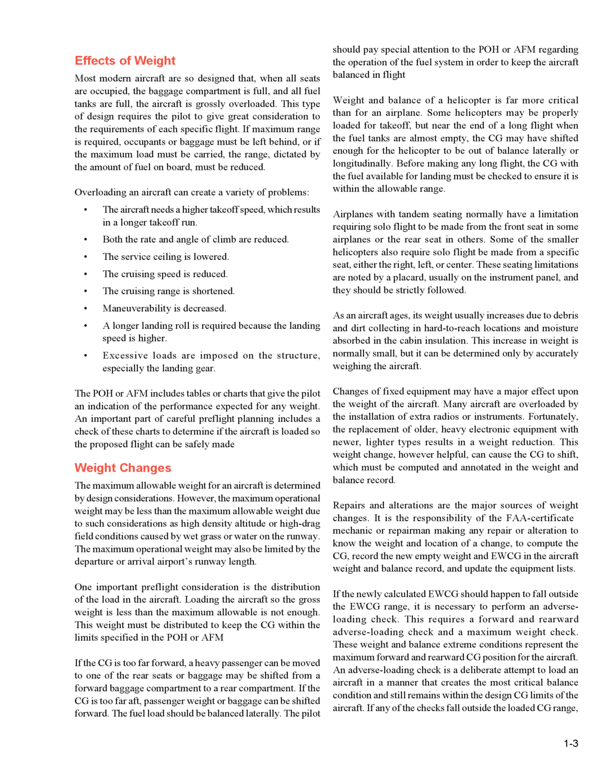This weight change, however helpful, can cause the CG to shift, which must be computed and annotated in the weight and balance record. Repairs and alterations are the major sources of weight changes. It is the responsibility of the FAA certificated mechanic or repairman making any repair or alteration to know the weight and location of a change, to compute the CG, record the new empty weight and EWCG in the aircraft weight and balance record, and update the equipment lists.